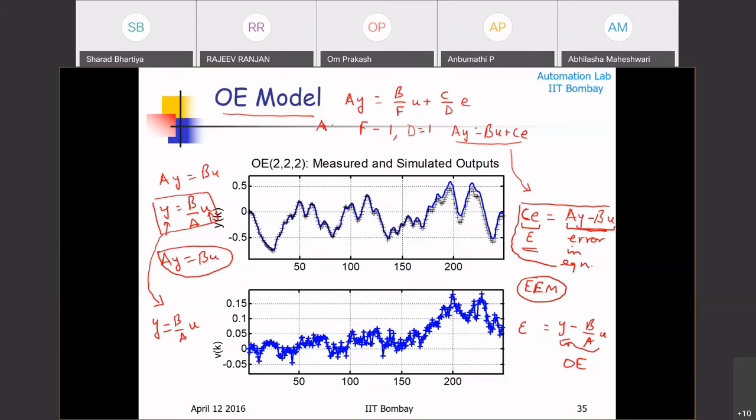If you were thinking in terms of a simulator where you only had some initial conditions and you wanted to do long range predictions, then probably an output error model works better. So shown here is an example of that output error model. I will also come to what these notations are, because they are going to be important when we look at the toolbox.